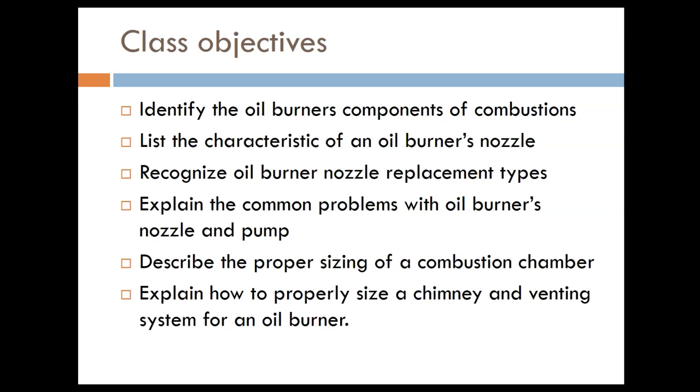There are a lot of old boilers that used to run on coal or heavy fuel that are being converted to regular oil, I mean number two fuel oil, or gas. So it's good to have an idea of what size of flame you need in that combustion chamber. Okay, we will explain how to properly size a chimney and venting system for an oil burner, and that has a lot to do with the code.